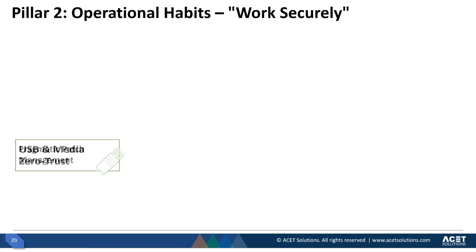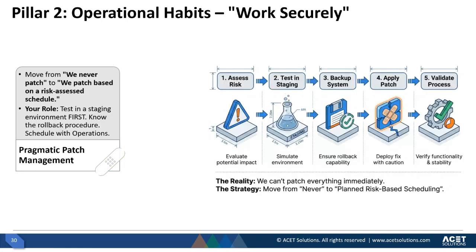Then we have patch management, which is also one of the biggest concerns for the OT side of folks. Patch management is important, but we also need to talk with our security team that we need to test that patch before implementing it on the control system environment. You have an important role to evaluate that the testing is completed, and to know whether we have rollback capability before applying that particular patch on the system.